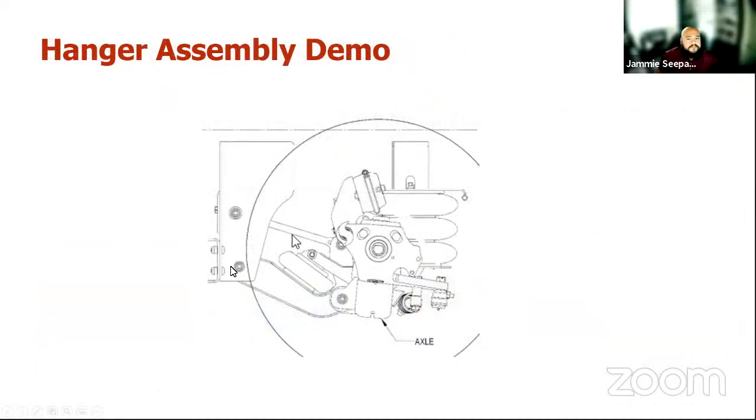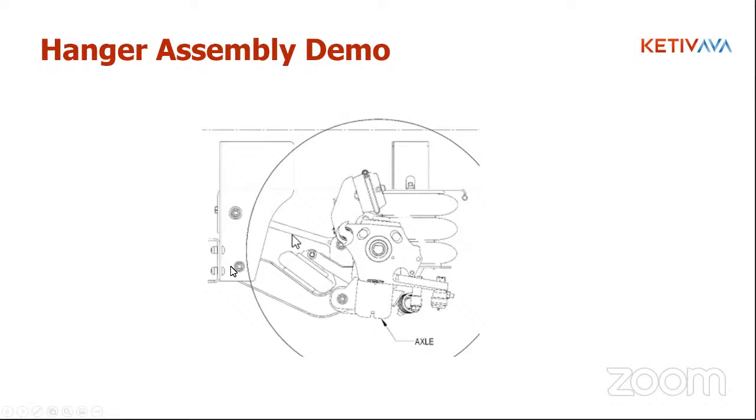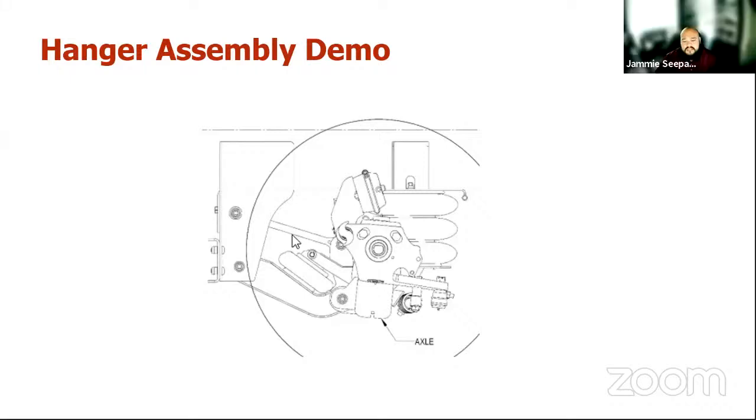Okay, so Jammie, so you use design states more as like a manufacturing guide. So we're going to do bend A first, then bend B. Maybe we'll then go put it on, do some punches. It was just mainly for like a guide. Correct. Yeah, you can almost take your manufacturing process as is, whatever your company standard is, and create that in different states and steps within Inventor now using model states.